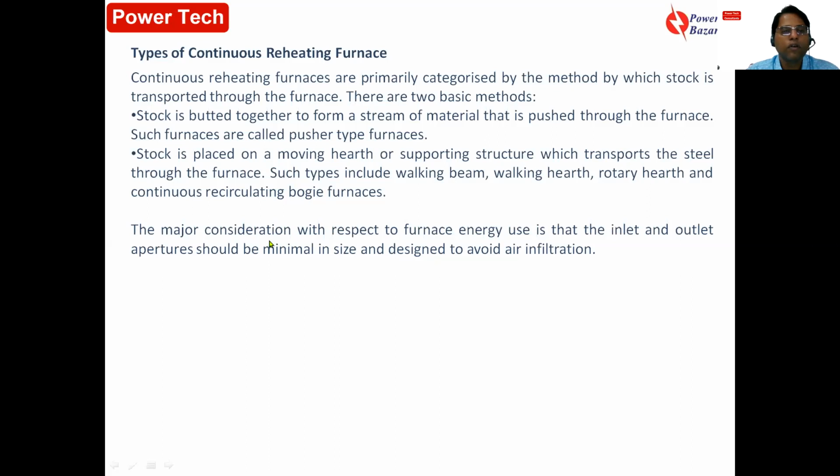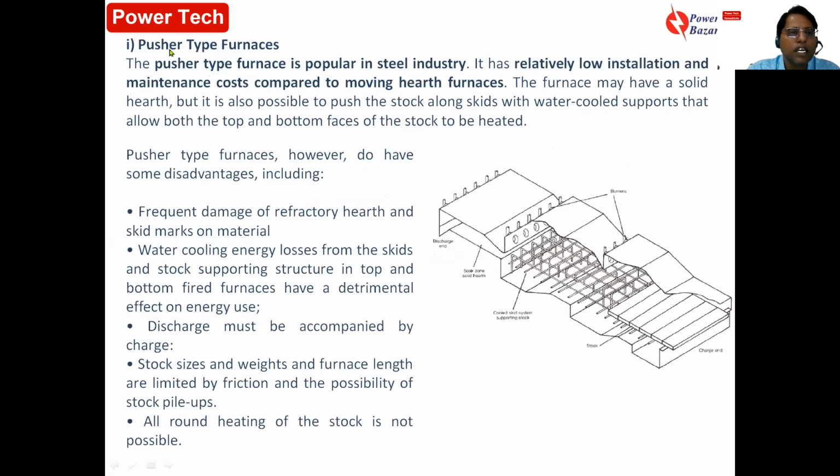Now, as I told you, the basic philosophy is that the inlet and outlet apertures should be minimum in size and designed to avoid air infiltration to increase the efficiency of the furnace. Now, see here, in the case of a pusher type furnace, what happens?